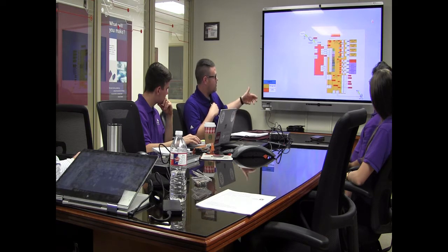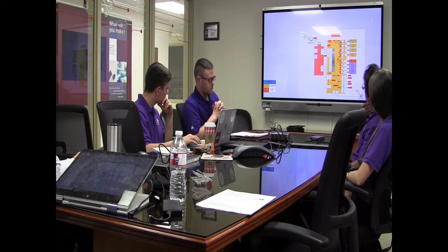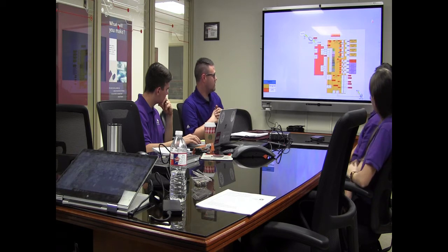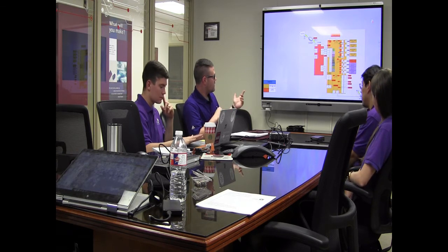We also have a pass-through directly to our ADC, and it's actually split down with a resistor pair, so it cuts the voltage in half so it doesn't overwhelm the ADC. And then we also use a GPIO for our motion sensor, and then additional grounds. And then there's our hotspot connecting through Wi-Fi, that can be connected to the board, and then up to Cayenne.